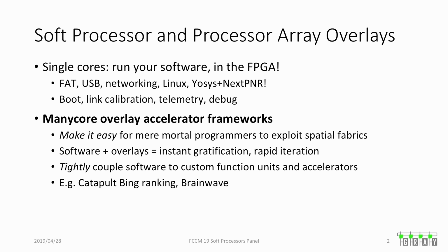My interest is in using thousands of cores in overlays to build frameworks to help software developers get their parallel software running in a spatial FPGA fabric. So how can we allow a software approach that still can light up and use 1,000 block RAMs or a couple of thousand DSPs per clock cycle? The use of software-first methodology and overlays means that the turnaround time per iteration is a couple of seconds to do the recompile, not 5 or 10 hours through the OpenCL to FPGA flow.